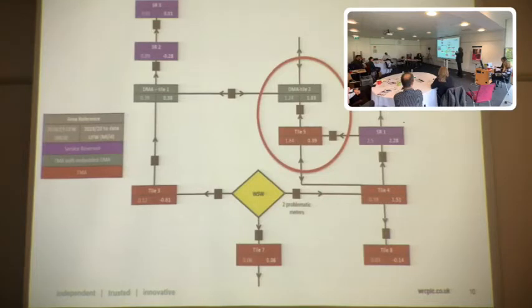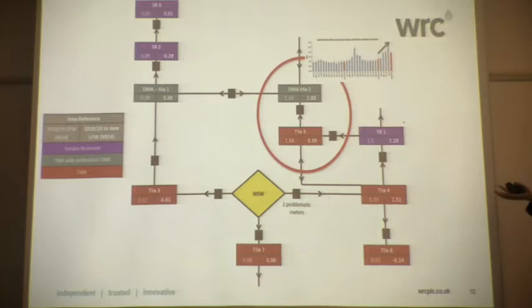I just wanted to highlight this example from another area. It's just an extract of an upstream area summarised, really. And we've got 2018-19 losses in the left-hand number box and 2019-20 to date in the right-hand boxes. Now, this company had previously not done any balance work across their upstream network, but they obviously have DMA level leakage estimates, etc. And we happened to include doing 2 DMA tiles in this because they had quite a significant amount of upstream network that couldn't be separated. And one of the DMA tiles looks a bit messier than you'd expect from an upstream one, but there are hundreds of customers.